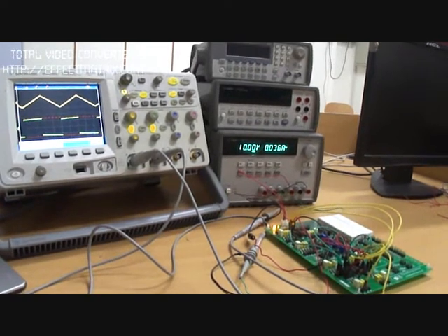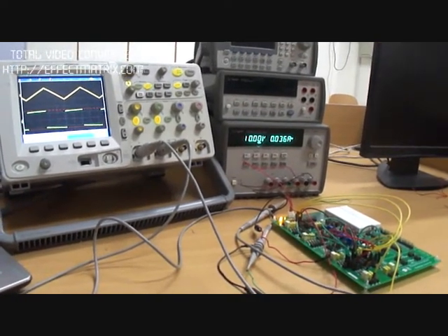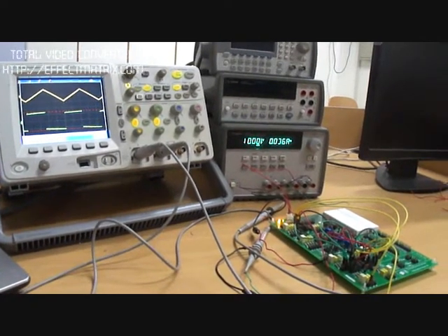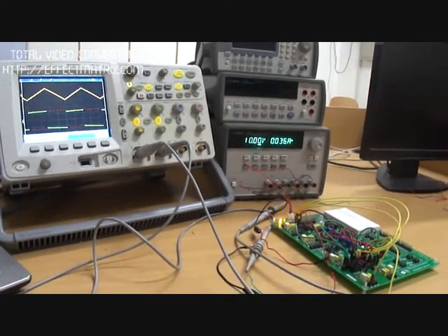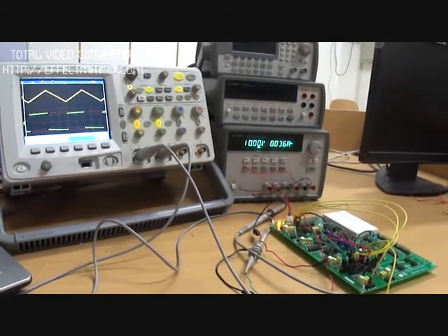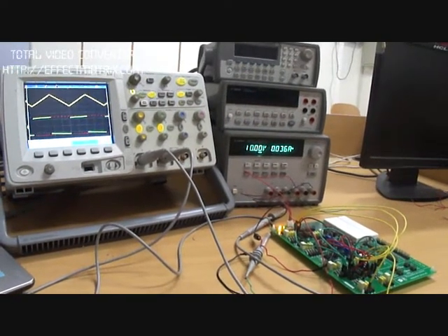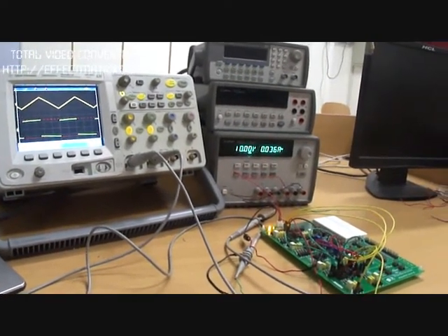As part of Phase 1A of the Analog Design Contest, we are tasked with studying a function generator that produces square and triangular waves. We were asked to derive expressions for the time period of square and triangular waves and also to measure their peak-to-peak amplitudes. This video will cover hardware implementation and simulation.